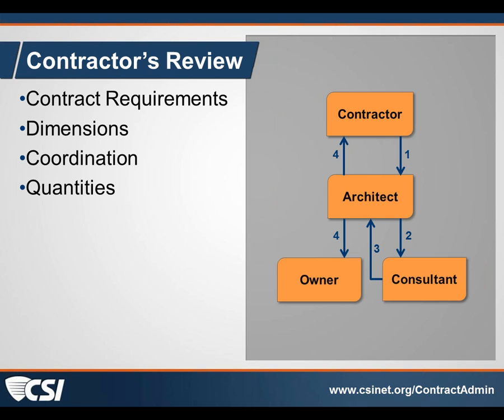Every time I get a shop drawing or submittal in and it's got a dimension circled and this is by architect or architect verify or something along those lines, I will cross out the architect and put GC in there. As Jim just said, the contractor is to review for dimensions, coordination, and quantities. That's not our responsibility when we review shop drawings.